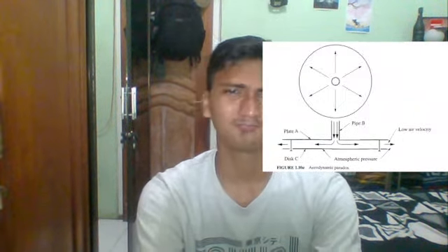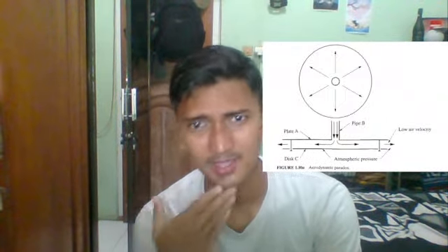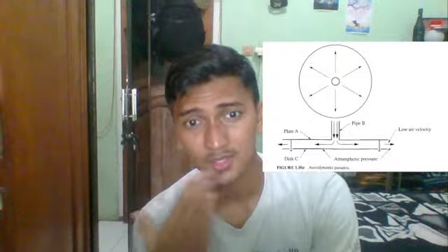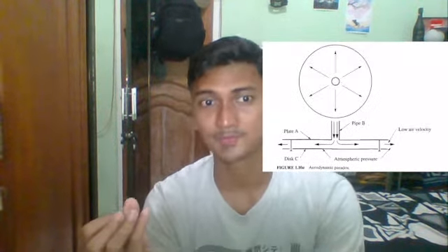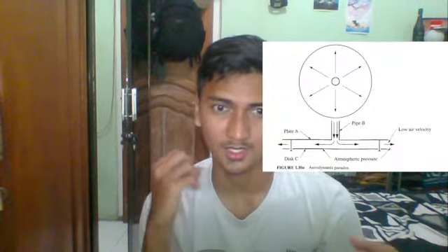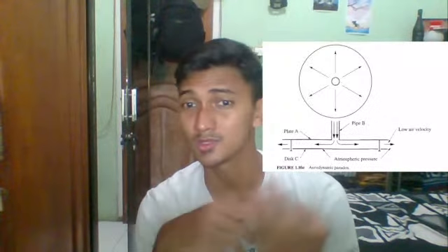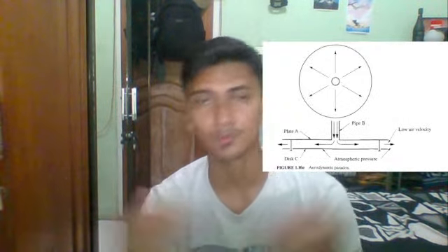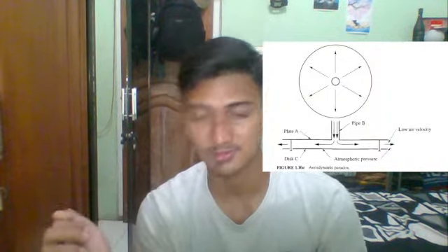As a result, the lower disc is lifted up against the upper plate. The moment the lower disc touches the upper plate, the airstream is stalled and the lower disc will drop again. That phenomenon will repeat itself again and again. That's what we call the aerodynamic paradox.